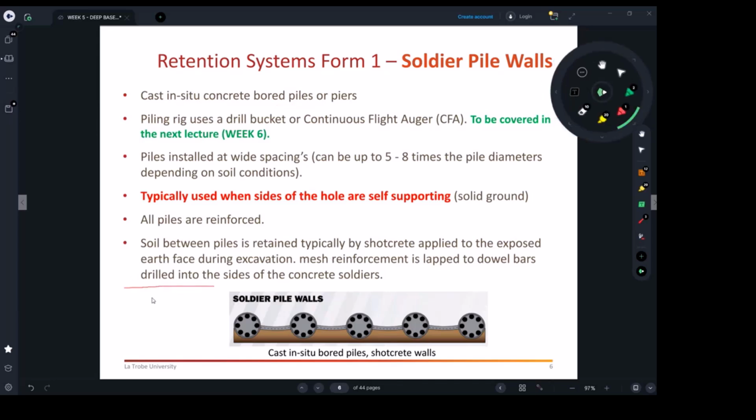This is the ground. We're going to dig for that 9-meter deep pile. In case you have a soil which can really be stable, like it was super clay with rock, and it won't collapse, yes, you are able to excavate the hole, right? And then put your steel cage.